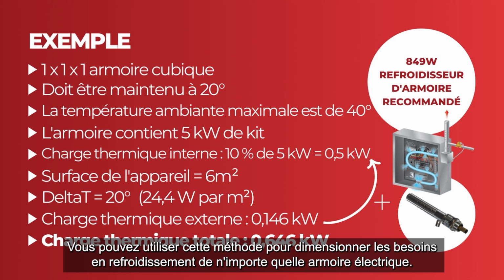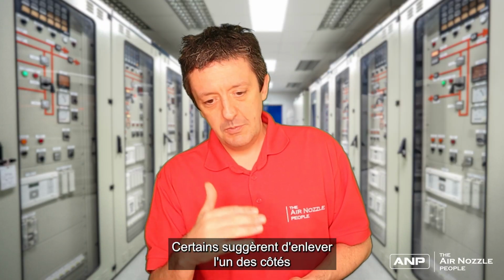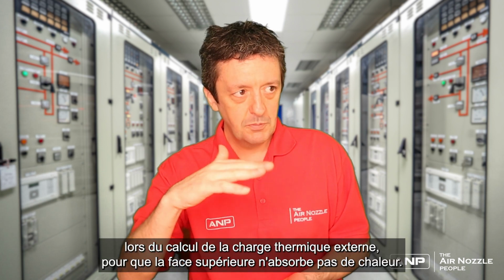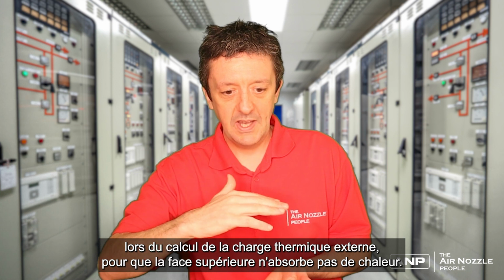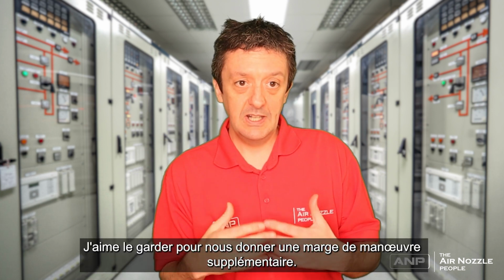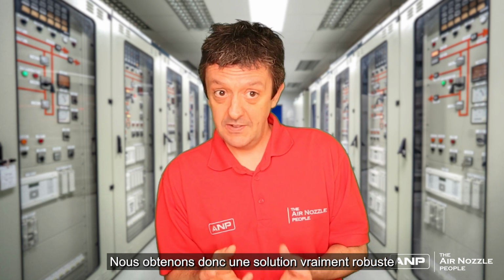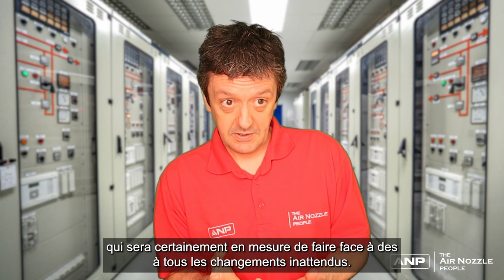You can use this method to size up cooling requirements for any electrical cabinet. Some people suggest that we take off one of the sides when calculating the external heat load, so the top side won't be absorbing heat. I like to keep it in, so it gives us a little bit extra leeway there, so we're getting a truly robust solution that's definitely going to be able to cope with any unexpected changes.